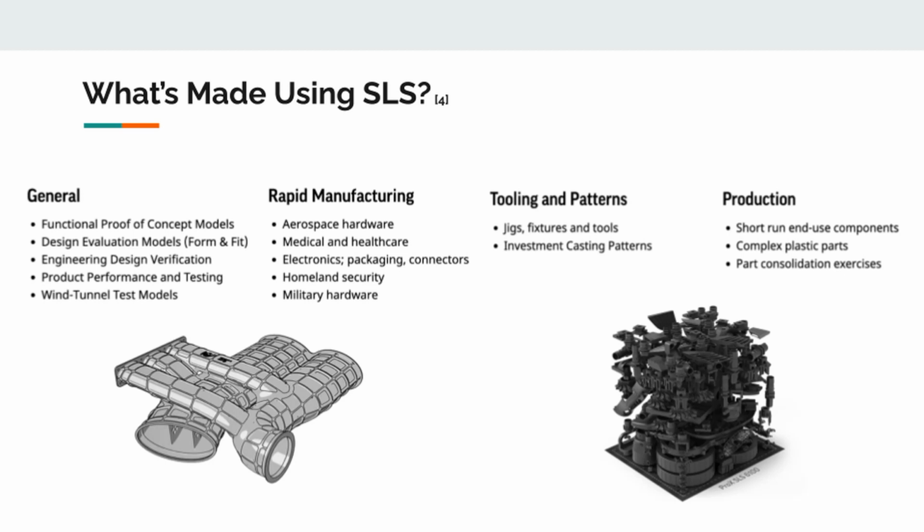SLS is also used in wind tunnel testing, where several scale models of a car or bumper product could be made and evaluated to see which design is best, and then later modified to incorporate all of the best designs and then reprint, retest to ensure success.